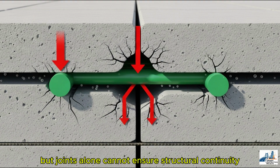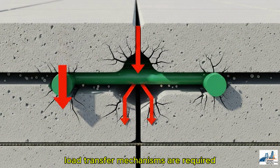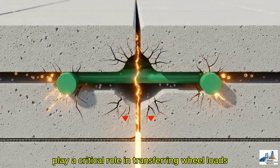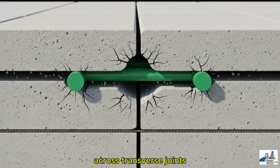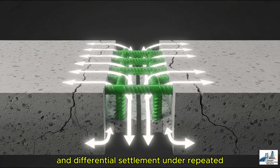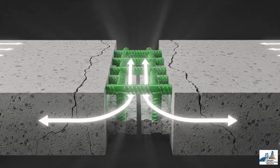But joints alone cannot ensure structural continuity. Load transfer mechanisms are required. Dowel bars play a critical role in transferring wheel loads across transverse joints. Correct dowel alignment prevents faulting, joint spalling, and differential settlement under repeated heavy axle loading.